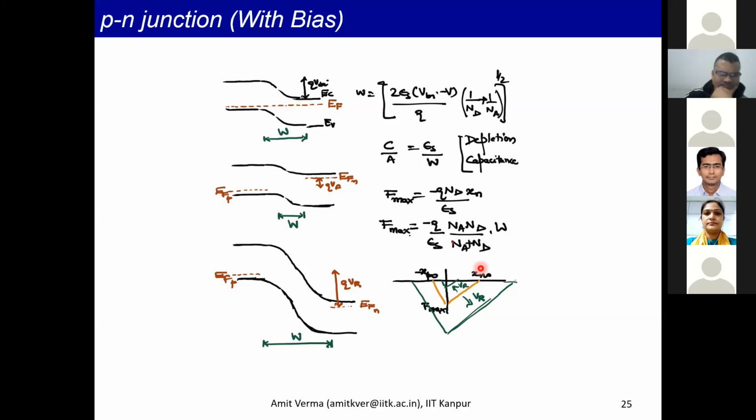The thing that gets changed is that you are starting with a different material, carbon nanotube, so the starting band structure is different. Carbon nanotubes are of many different kinds, I think semiconducting and metallic. Depending on the carbon nanotube you start with, you need to know its band structure. Then you dope it. Once you know the band structure, you know the density of states. Based on that and the doping, you can find out how many carriers you have in that material. And then, following the same process we have been doing, you can make a band diagram of the PN junction.